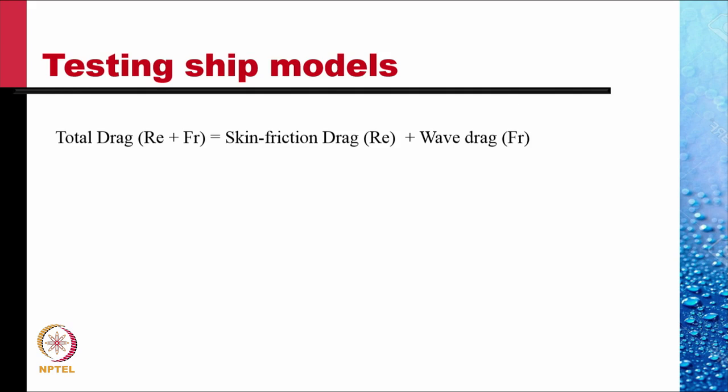Now, skin friction drag is a well-studied topic and can be estimated from the skin friction on a flat plate. The sides and the bottom of a ship can be modeled as flat plates, and skin friction on them could be obtained analytically using the correlations for flat plates.